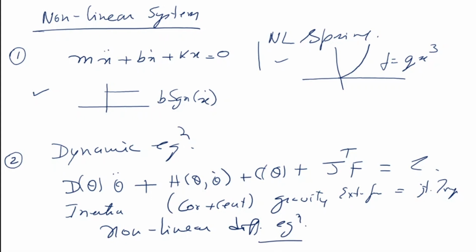So it basically means that the equation of motion of a robot manipulator is a nonlinear differential equation. Although we talked about linearizing, we can only linearize the system at a point, but a robot manipulator is going to operate at different points. So trying to linearize it about one point in the workspace really doesn't help. The other way is to use the partition control system.